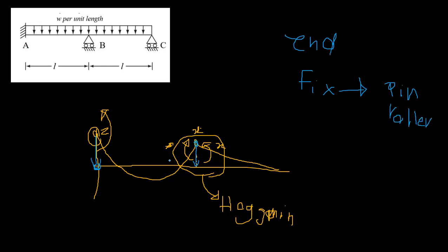Then you release the moment. It can rotate, right? So if it is an end, you don't need to worry. How we are going to release the moment is, you just apply a pin support here. So then you release the moment. It's like theoretically you literally removed MA, right? But still RA is there. But the moment you remove that, this RA and the earlier RA are not the same, so the structure is not the same anymore.